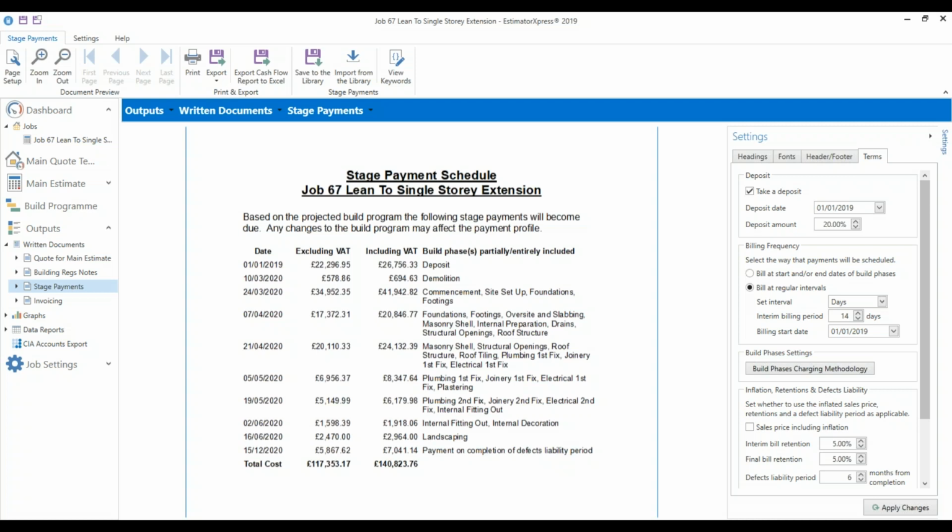All cavity trays are already taken up in the roof section, so they're already allowed for within it. That's about understanding the allowances and what the software is applying when you're estimating. So what I'd suggest is taking some time to go through the dimensions and the resources while you learn the software, so you have confidence that the software is allowing for those different sections. Cavity trays are definitely taken up in the estimate, especially under the roof section.